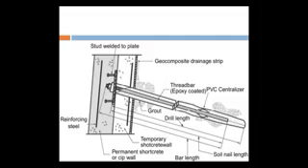First we have to drill, then provide grouting, then steel bars. Epoxy coated, a PVC centralizer, geocomposite drainage strip, temporary shotcrete wall, reinforcing steel. All the components of the nailing have been shown.